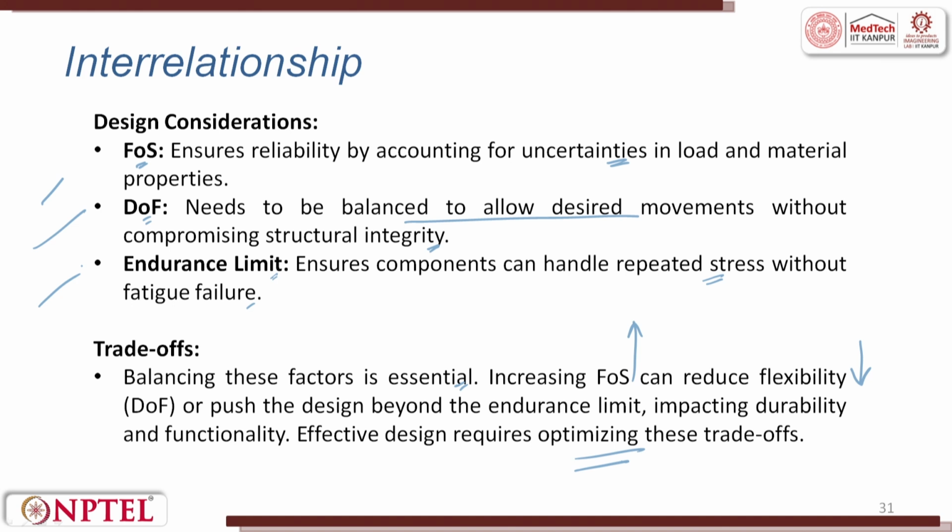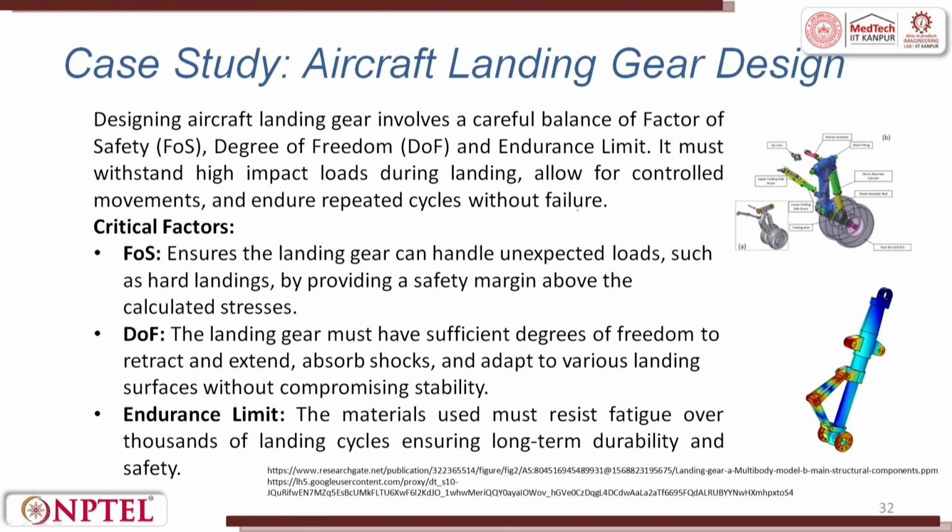FOS talks about stability, a strong system. The degrees of freedom allow the desired movement without compromising structural integrity. If you make it heavier and have a lot of movement, then the system becomes inefficient. Endurance limit can handle repetitive stress. So, you should try to have a balance between these three when you are trying to develop a structure or a system. Let us look into a case study, an aircraft landing gear design.